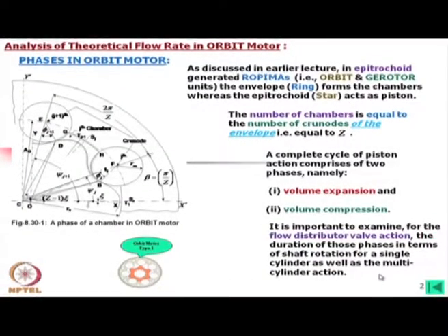It is important to examine the flow distributor valve action. If we analyze the flow distributor valve action, we need the duration of those phases in terms of shaft rotation, for a single cylinder as well as for multi-cylinder action. So, what we have to do is analyze at what shaft rotation angle the bottom dead center and top dead center occur, and the distributor valve should act accordingly.